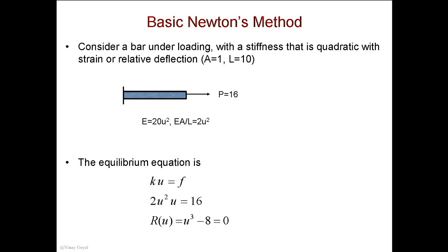So in fact, when you're solving with Newton's method, you're trying to find equilibrium. And that's what Abaqus tells you: equilibrium iteration 1, equilibrium iteration 2, 3, if you look at the message file. It's because you're trying to solve to get equilibrium, so that the internal forces in the body equilibrate the external force applied of 16 pounds.